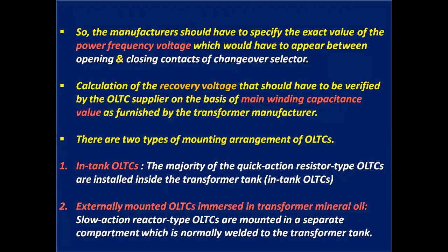Calculation of the recovery voltage should be verified by the on-load tap changer supplier on the basis of main winding capacitance value as furnished by the transformer manufacturer.